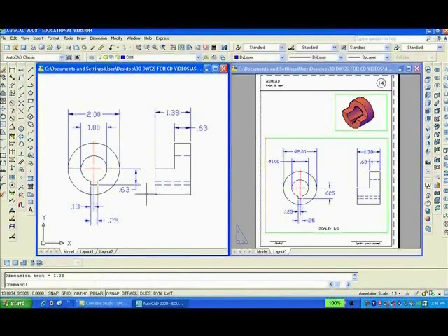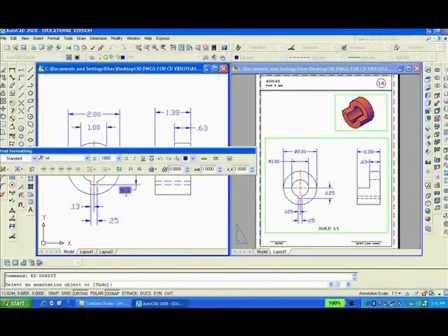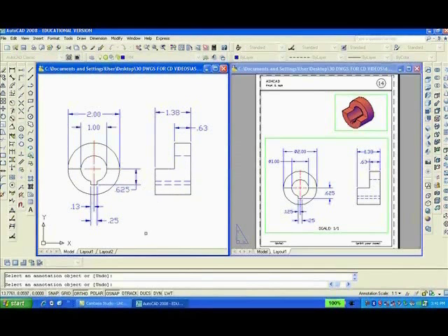Of course, if you want to change something, you can type ED, enter, edit. I can delete that and type 0.625 and click OK, etc., etc. Also, you know that if you want to, you can click on the grips, get rid of ortho, get rid of O-snap, and just drag it up to wherever you want it.